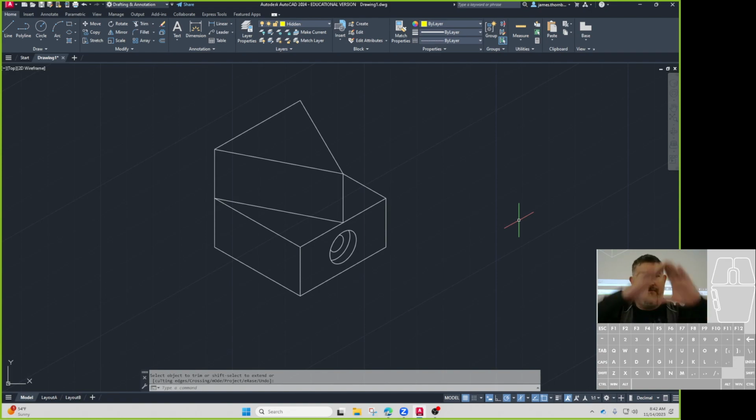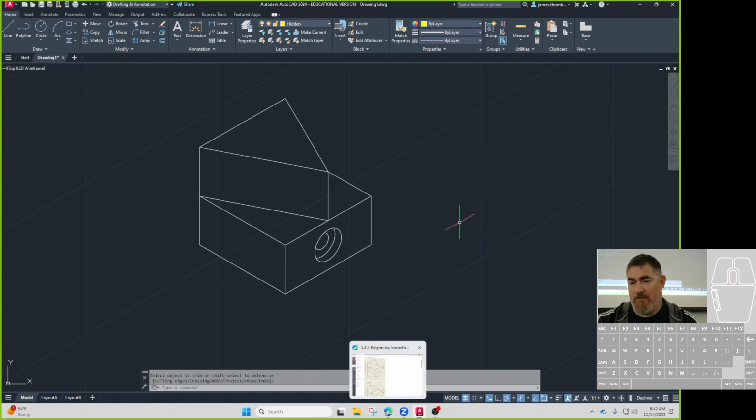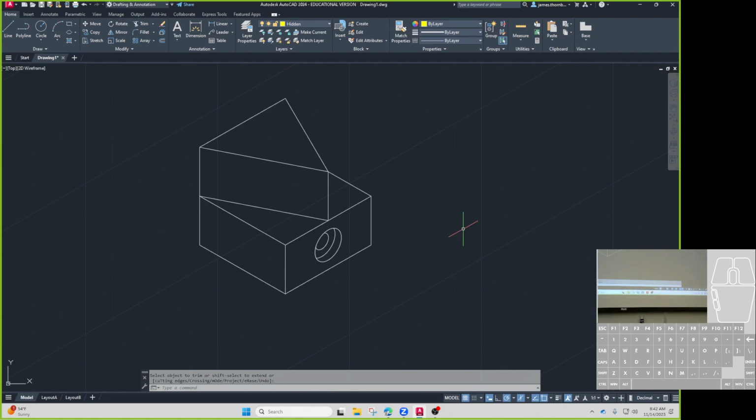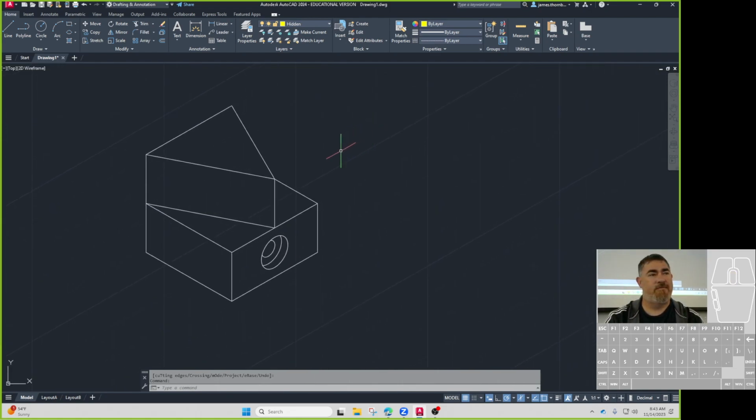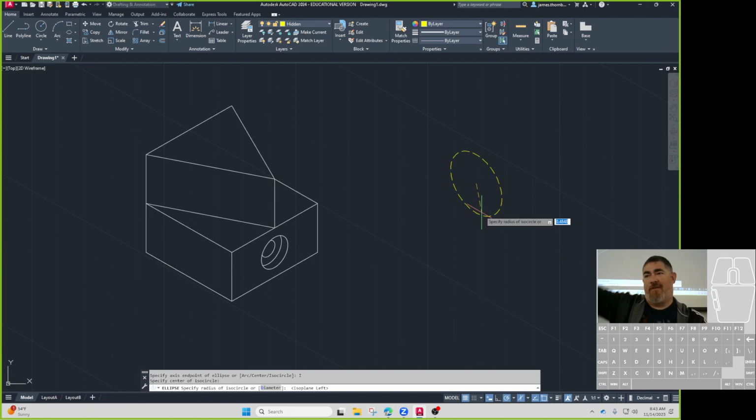What if I was doing some kind of outside cylinder? So like, you know, I want to draw my water bottle. Let's say I just want to draw a cylinder like this, a positive cylinder, not a cut negative cylinder. How would I do that? Yep, so ellipse, Isocircle, pick here. And so I can tell which way I want to go. Wrong layer, but let's say I want to go the opposite way there. Go there. I'm going to say this is diameter 3.